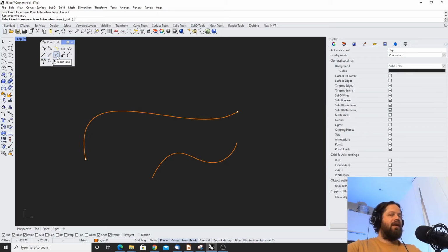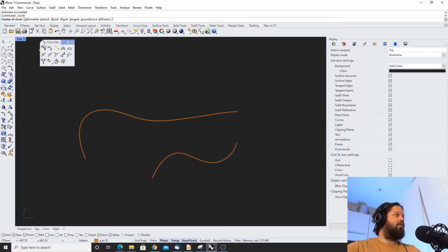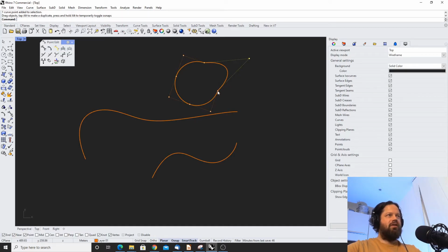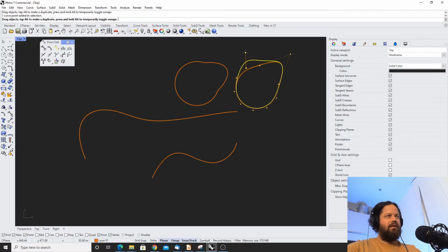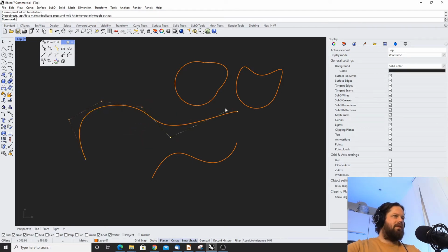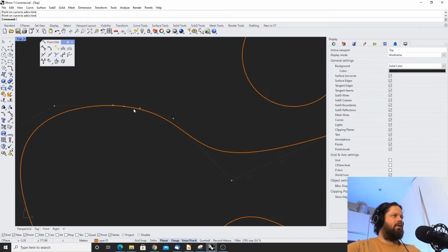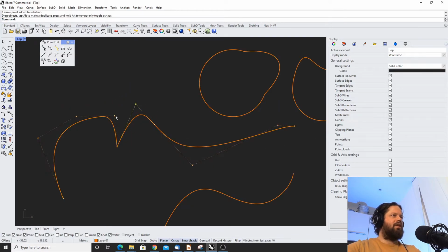Then you have the kink option. As you can remember, there's the way that you draw circles. So you can draw a circle like this, and now when I move one of these control points, actually it creates a kink because these are arcs. And if I use the deformable option, then I actually have something like this. And the same actually is here. Now these are all static, or static is like a continuous curve without any kinks. So I can add kinks by using this one. That creates me actually 2 control points.